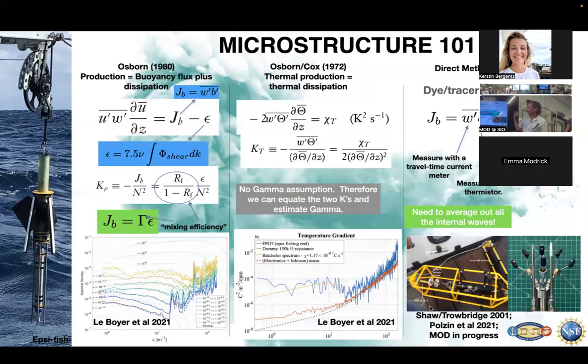Touched on it, okay. So one of these methods starts with what's called the turbulent kinetic energy equation. I can do a Reynolds average on the equations of motion, and I can write down equations for the turbulent kinetic energy. Then I would get this expression if I throw out about nine terms. If I assume that there's no time dependence and not a lot of lateral transport, then